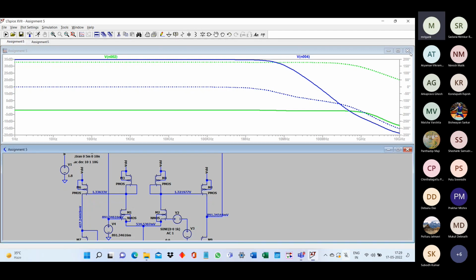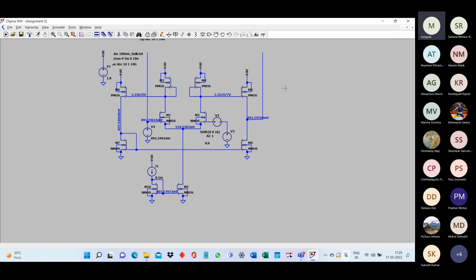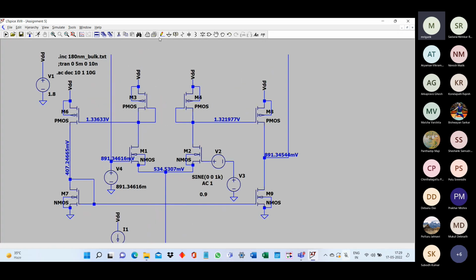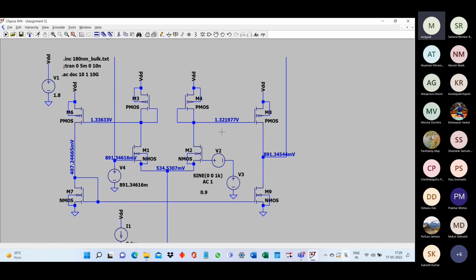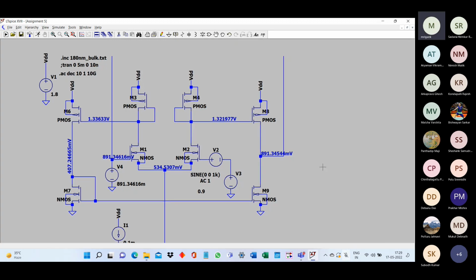Since we have got rid of the R, that is also changing the gain magnitude a little bit, because R also has some loading effect. Remember, this R we put only for the purpose of getting a DC bias for our open loop analysis. There is no other purpose. It is an artificial imposition. So we have got rid of the R and just imposed the right DC value with which we are getting a proper DC at the output. This is not the actual way in which we can bias the circuit. This is just to simulate the open loop condition. That's all.